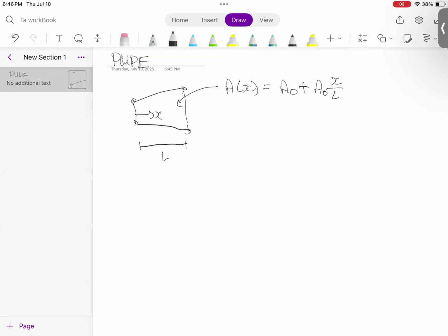So first of all, step one: we follow the finite element method. We need to discretize this bar into elements and nodes. So we have nodes 1, 2, 3, and elements 1 and 2. Then in step two, we first define our energy function.